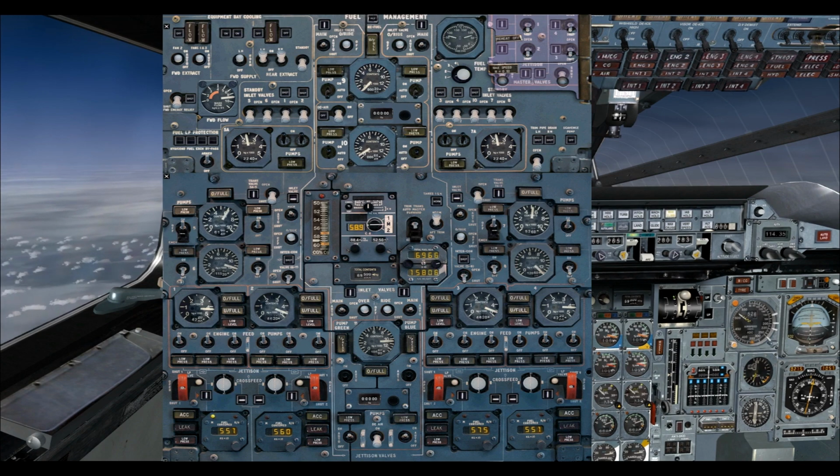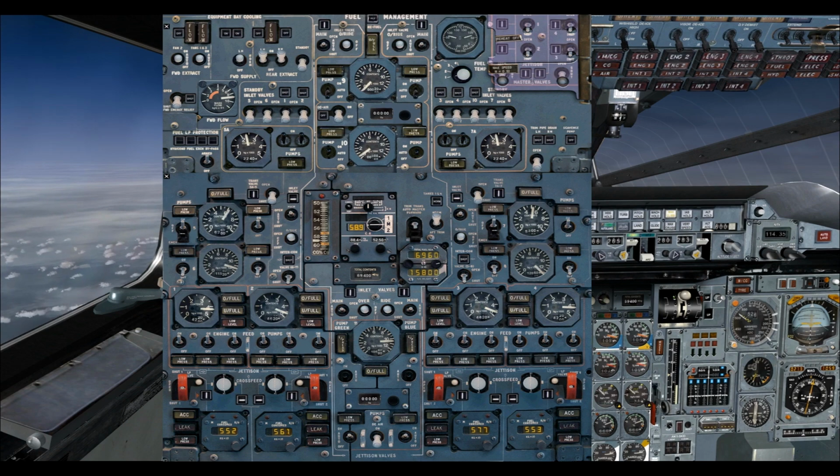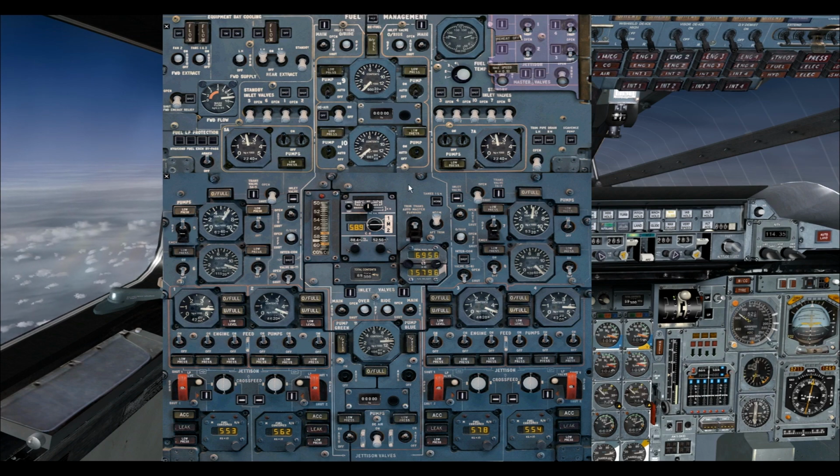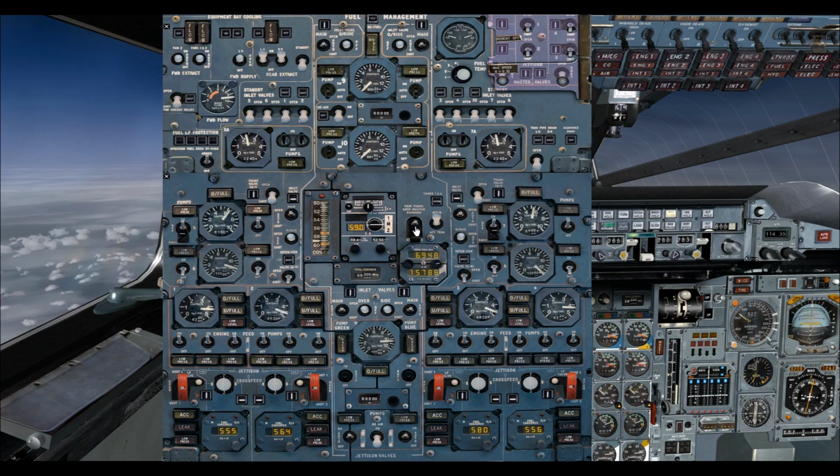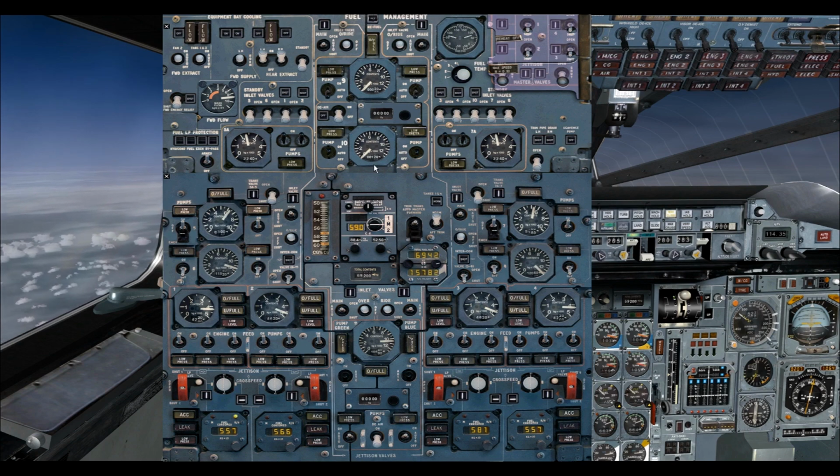We're approaching the end, 58.9. Tank 10 will probably empty out almost completely by the time we stop the transfer today, based on the way our fuel is set up. So I'm just waiting for the fuel transfer to complete. And there we go, 59. So I'll stop the fuel transfer at 59.0, and tank 10 has a little bit left, 120 kilos. We'll leave that there for landing.